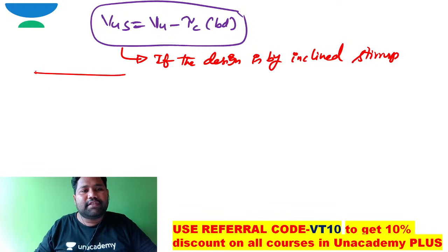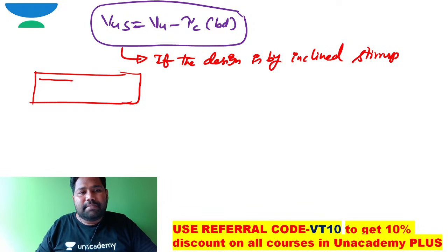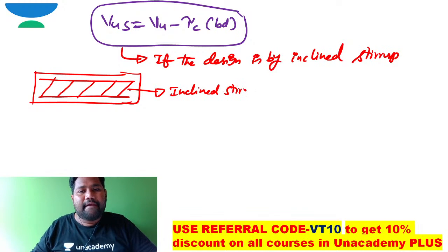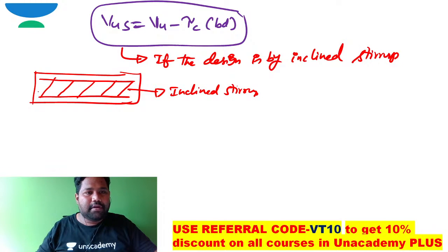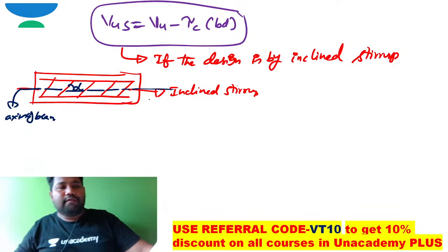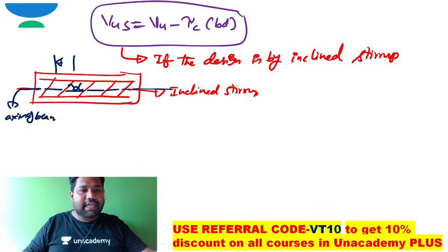if this is the beam, for example, this is the main reinforcement, and this is how the inclined stirrups are placed. These are inclined stirrups. I hope you are able to see the axis of the beam. If the angle made by these inclined stirrups with the axis of the beam is alpha, in such a case, how can I work out the spacing of these inclined stirrups?